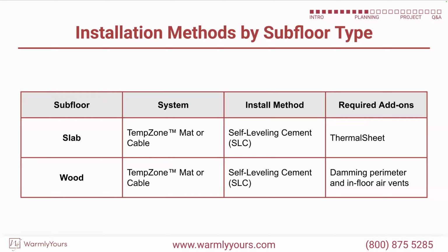Now, talk to us about the differences between a slab, why it's so important for us to know what this is going on, slab or wood. Yeah, so when you're doing that over concrete application, you're on an existing concrete slab on grade foundation or something, that is important because what that slab is going to do is suck down some of your heating. So in order to prevent heat loss and get you a more energy efficient floor, a better performing floor, be able to turn it up to a little bit warmer temperature that you'd like, you're going to need to use what we call a thermal sheet if you're on top of a slab.